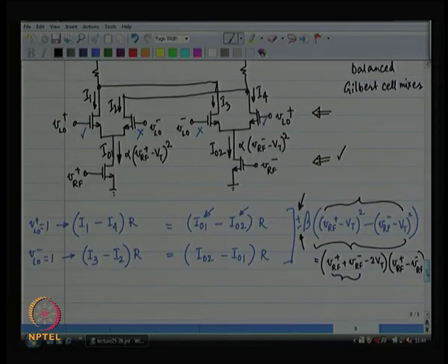How do you linearize a circuit? So, think about this. You apply V in over here, small signal, and the output you get, if V in is a small signal, then the output is minus gM times R parallel rDS times V in. Now, this works only if it is a small signal. If V in is a large signal, then gM itself is going to vary, which could be our case, and then we are in trouble.